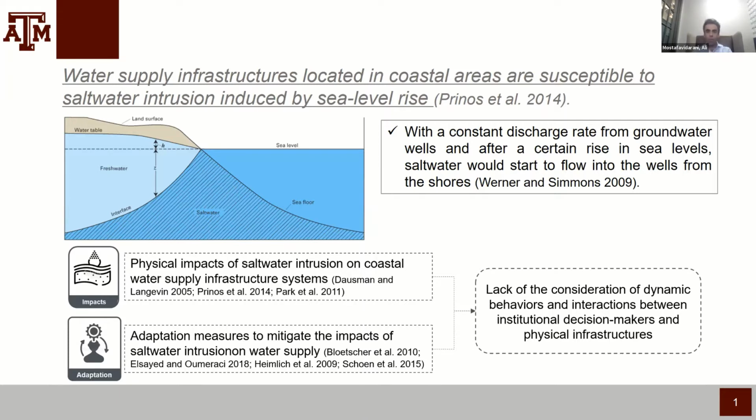These are things that I learned from my dear colleague, Dr. Suka, who is on the webinar today, that this increase in sea level rise and depletion of groundwater creates a hydraulic difference that accelerates the saltwater intrusion into the aquifers. And this increased salination reduces the capacity or availability of fresh water supply, and it requires making decisions and taking actions for dealing with this, either to change the location of the well fields to take them further away from the salinity lines, or increasing the capacity of the treatment plants so that they can have desalination technologies to remove salt water from the groundwater.